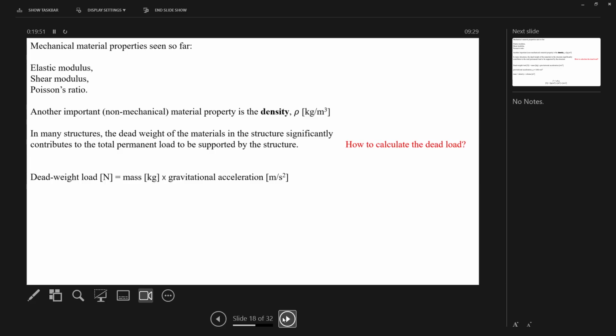And the reason why we have that terminology, so when we're writing our calculations down, we're being consistent. So we should get our heads around permanent load. Permanent load, what would that be written down as? Does anyone remember? No, I'm totally off topic now, but we're here, so we'll talk about it. G_k, capital G, meaning G means permanent, Q means variable. You heard this before? Right, and k means characteristic. So it'll be a small letter k but subscript. That just means it's characteristic value, right?